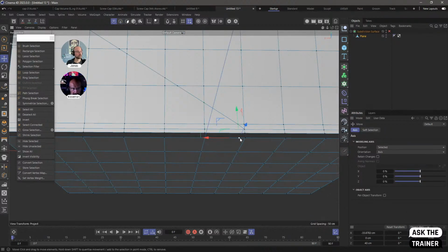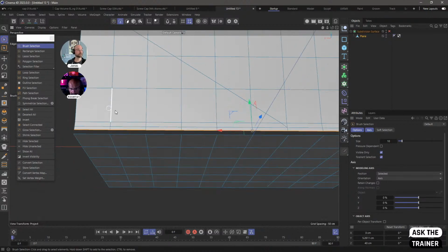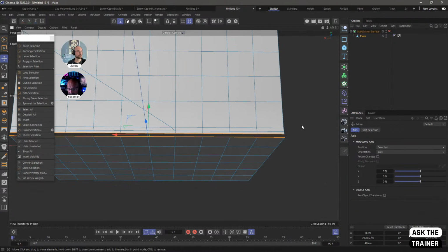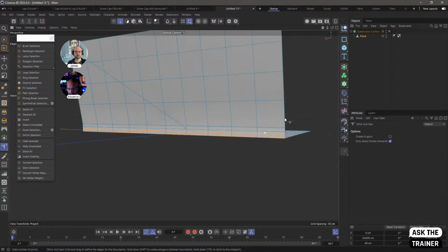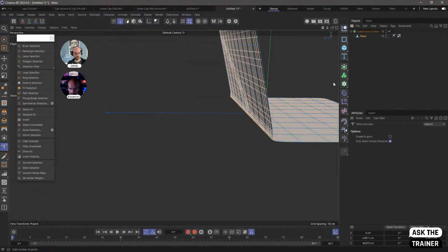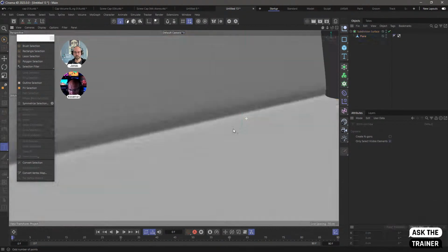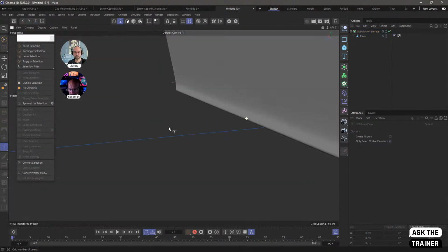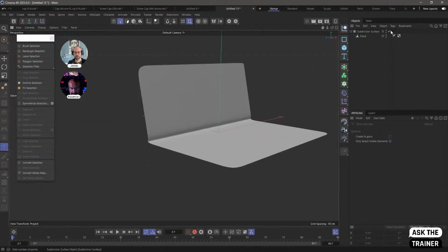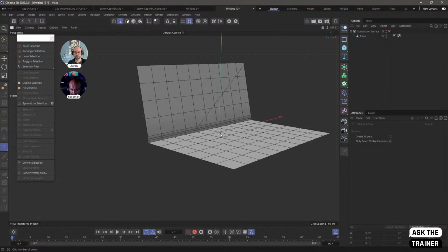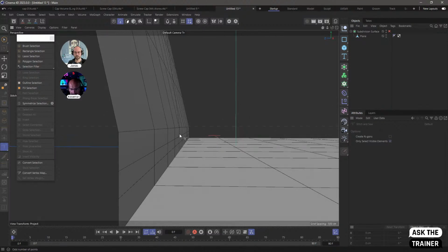Now I can use the magical stitch and sew. So move tool, shift, double click, right click, stitch and sew, and press shift and do that. And what happens now is that under the subdivision surface object, although that thing exists, the curve does not give us any artifact. So having the transitions happen in places where you're not actually bending, which this is wrong because it's bending here. So I should have done it properly.